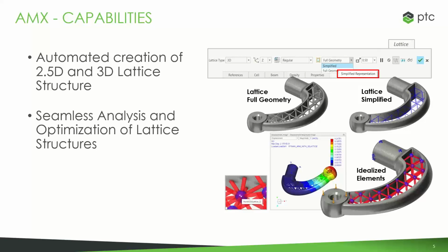It's really moving away from those more over-engineered designs, those kind of blocky designs that are just going to pass by the time they get to validation. So moving away from that, and once you've optimized the structure, take it into analysis. See the stresses, see the deformation, check out the temperatures, whatever might be important for you to go ahead and improve that design, really start to optimize towards a much better design overall.